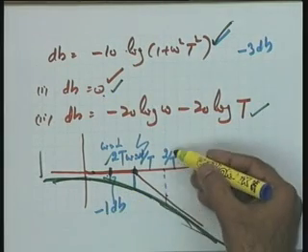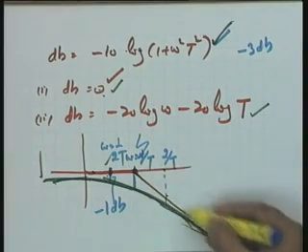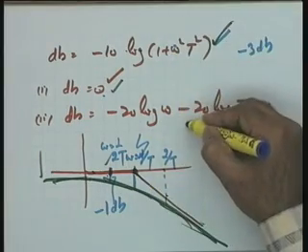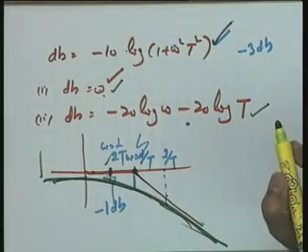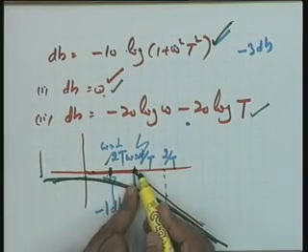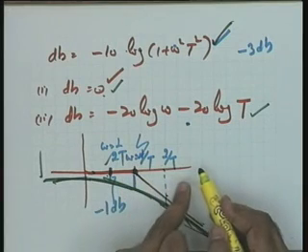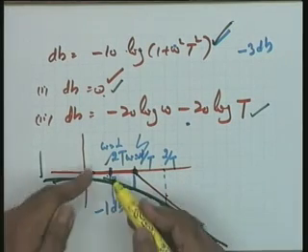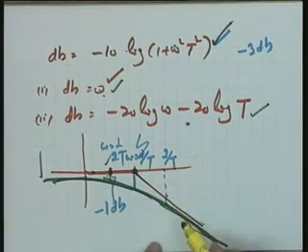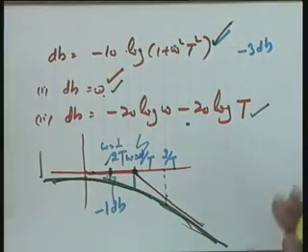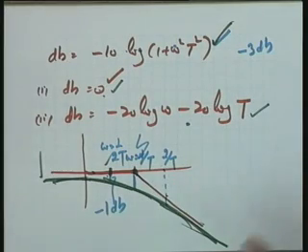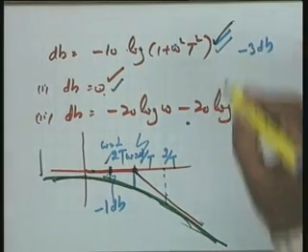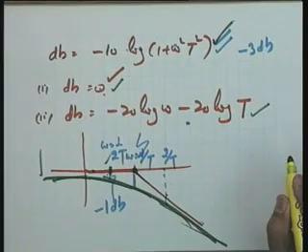You put the value omega is equal to 2 by t and take the error between this plot, this value and this value. Now, you will find again the error is minus 1 dB approximately. So, at frequencies 1 by 2t and 2 by t, the errors are minus 1 dB here and minus 1 dB here, and these 3 points are found quite adequate to make the green plot, that is, the correct, accurate plot for this particular system, which takes care of the approximations.